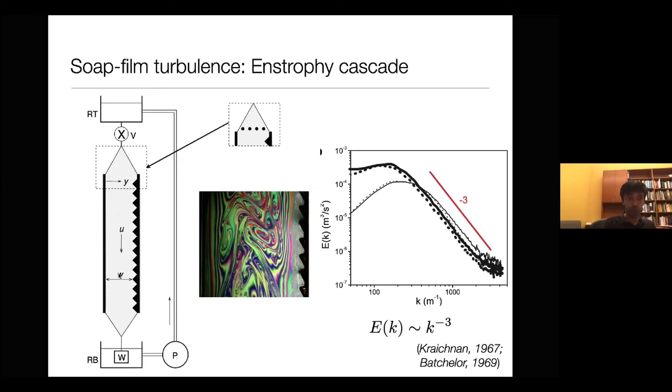And so the flow goes down between these two parallel walls. And at the end of the channel, you collect it back using nylon wires onto another bucket. And then you use a small pump to push this thing back. And here you have a recirculating channel flow. But this channel is quasi two-dimensional because the thickness of the channel is orders of magnitude smaller than its width and its length. All right, so what do we do?